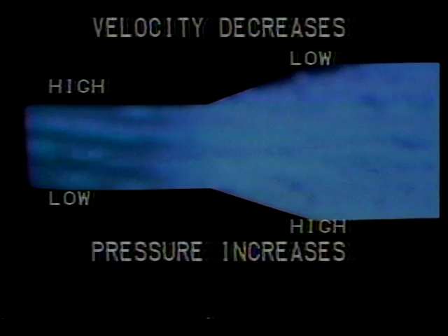Now, whenever air is forced through an enlarging air path, the velocity decreases while the pressure rises. It's at this point in the spaces between stator blades where air is slowed down and we gain air pressure. This is called diffusion, and it is the key principle which makes the compressor work. The space between rotor blades acts as a diffuser too, slowing down the air velocity.